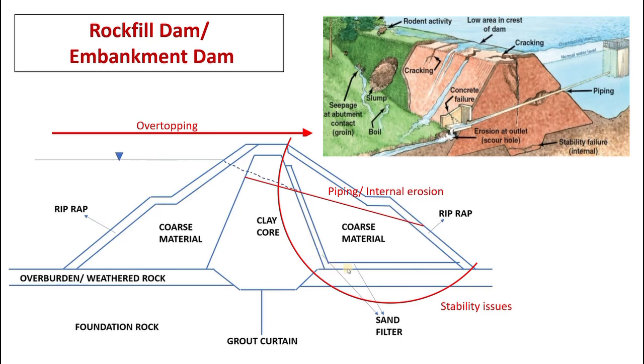Seepage causes loss of material from the dam, which may enlarge the gaps, which ultimately increases the water pressure, and this causes slopes to fail. Sometimes, settlement of earth in the dam also causes overtopping as available freeboard reduces. Earthen dams are more vulnerable than concrete dams.